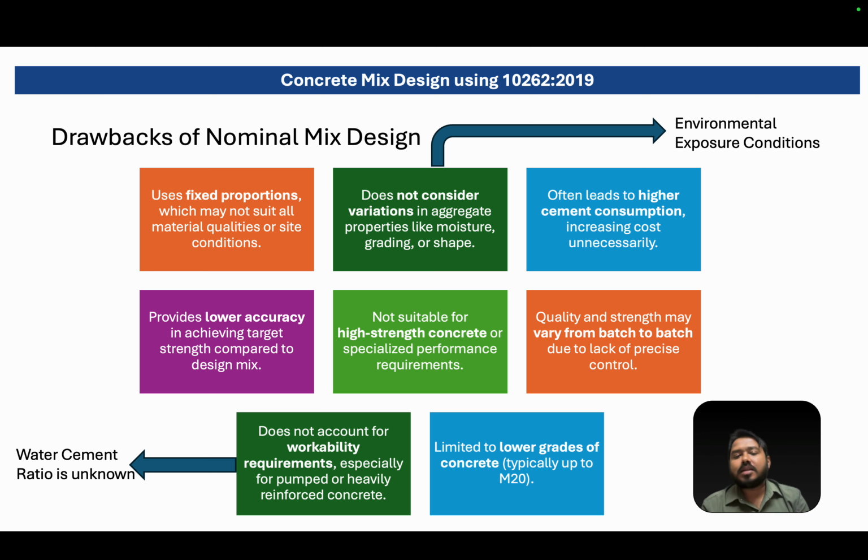That is why there is a drawback in the nominal mix. And the most important thing, the major problem, is that we are not going to consider any kind of moisture, that means any kind of environmental exposure conditions. There are different exposure conditions, mild conditions and severe conditions, whether you are designing for normal concrete or for reinforced concrete. So all these things are not inclusive in the nominal mix design.